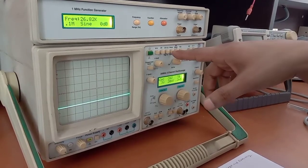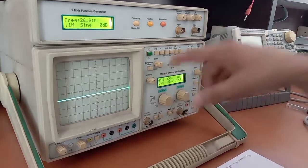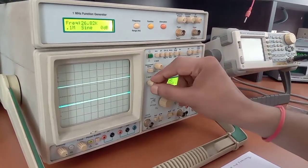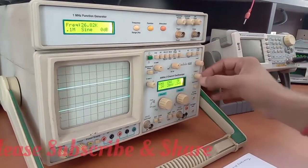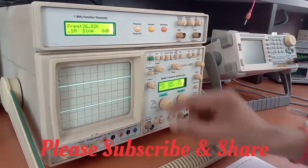This is mono and dual. So when we unpress it, this will show mono channel, a single channel. When we press it, it will show two channels. So there are two channels. This is the vertical direction of one channel. This is the vertical direction of the second channel. Now these are the Y shift and X shift.